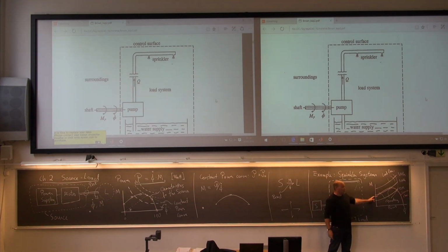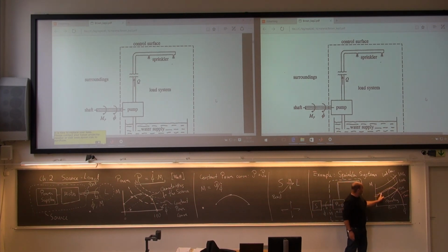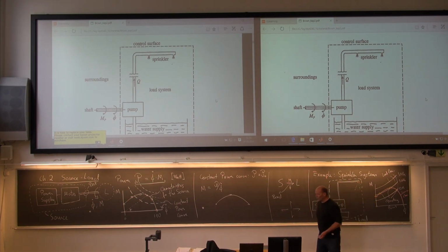And you see, it's too weak. So nothing is going to happen, well, except that you probably burn up your motor. So this is a very, very bad idea. If we could get past the first operating point, then it would be okay. Here, our motor is strong enough. So then we could accelerate, reaching this operating point. That would be okay, but no, you can't even get things starting here. Big problem. So we will now see how we can remedy that. Any questions?